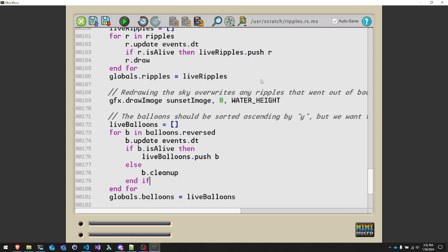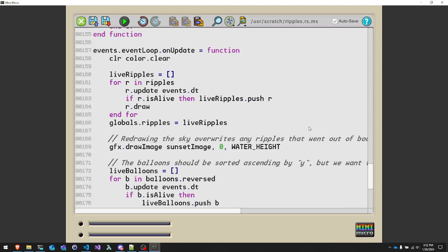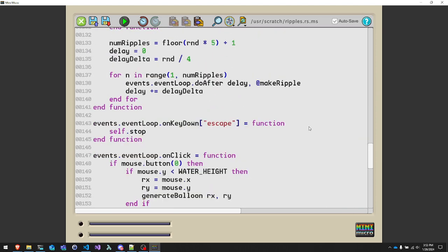You basically have sprite images sitting in memory, and then there's another chip alongside the 6502 inside the old NES that would pull sprites from sprite memory and handle all the rendering and updating of sprites for you. So all the sprite processing was offloaded to another processor, which is actually pretty cool. But the point is it's automatic and it's fast. So you should try to use it if you can.